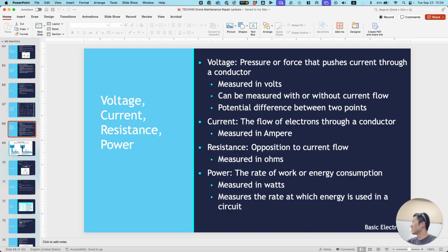Okay, that's basically going to tell you how much current this battery can handle, how much it can supply. If you use a low C rating battery on a drone that requires a higher current, you're basically going to brown out. It's going to try to draw more than the battery can supply. So it's important to size up accordingly. We'll go more into detail on that. Don't worry too much if you don't understand all the numbers on the battery. I'm trying to slowly introduce some clarity because there are so many numbers on this thing.